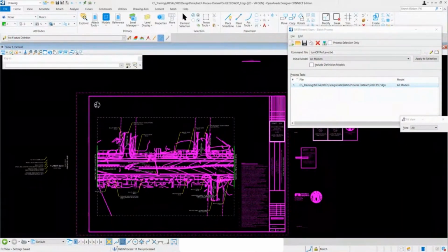So the sheet DGNs have already been cut, right? And since they're already set up, each sheet DGN will be in a different location and in a different orientation based off of the roadway alignment. However, I can leverage the fact that the DGN with the legend was created right at the XY equals 0,0 coordinates. So I'm going to use that to quickly place this new reference attachment in the correct location and orientation.